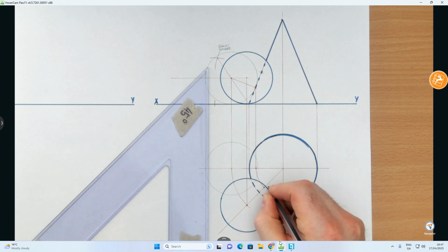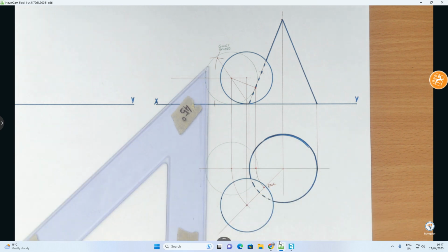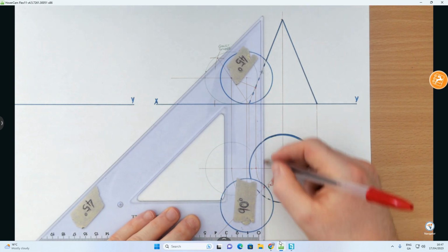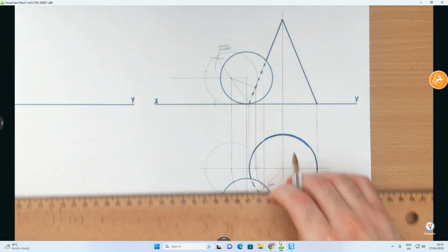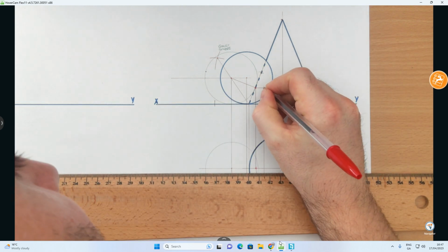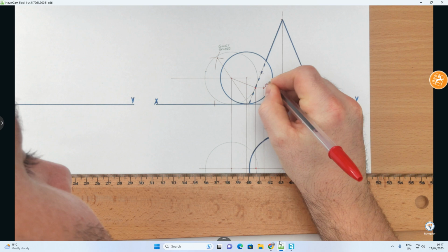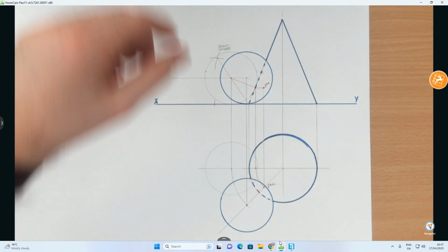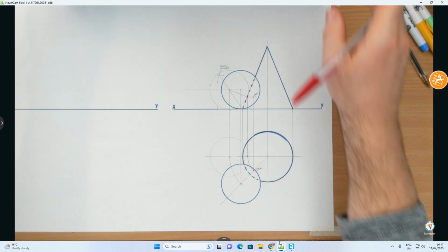Right there now is our point of contact located with the letters P, O, C. Now that I've found them in the plan, project it up, and the point of contact will stay at the same height and elevation, so just bring it across here. That's the one I'm going to locate as P or C. Okay, so there you have it. There is the first question completed, guys.